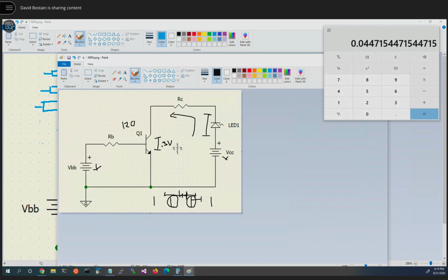So this is the sort of thing that will change, maybe not everything. Maybe all I do is change beta. I won't change this value to be anything other than 0.7, although let's assume that I gave you a value of 0.7 here, and I said the other value here is 1 volt. If you knew there was 1 volt across that, we're not saturated. We're working like an amplifier.